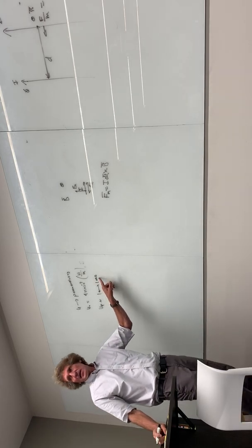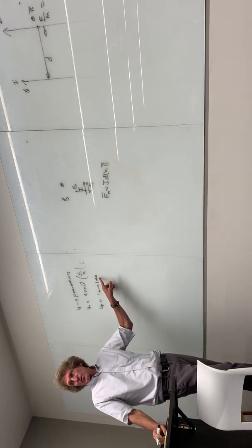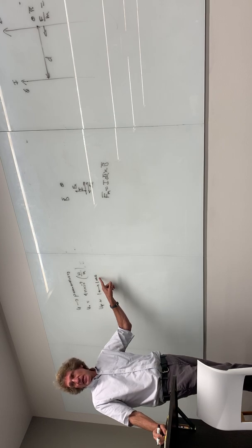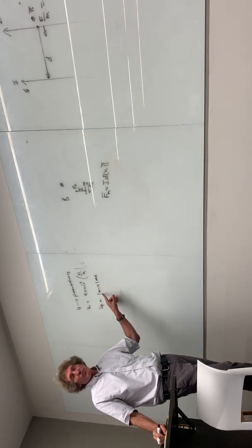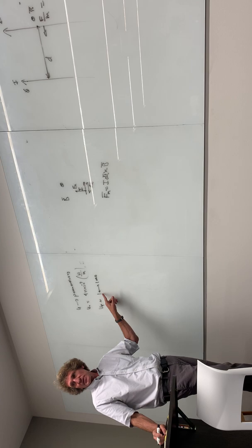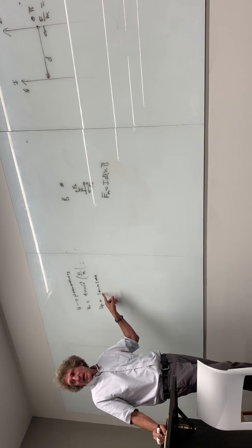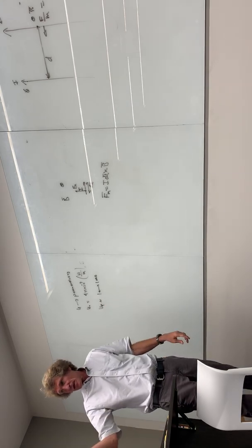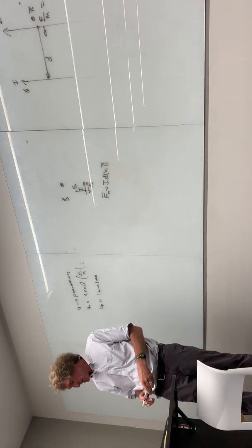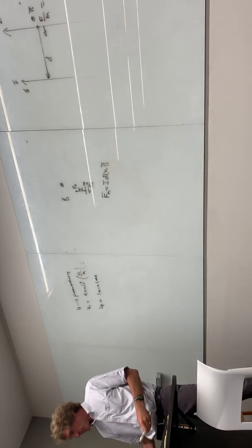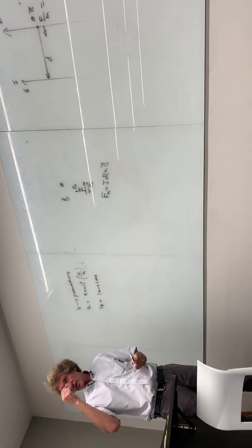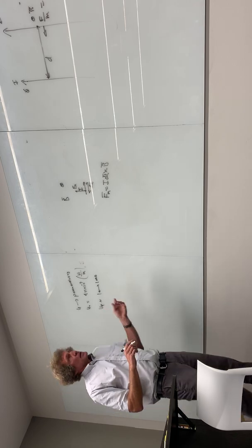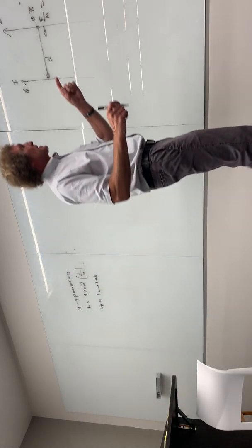For instance, any kind of thing used for iron cores for our transformers is about 1,000. It's laminated steel, it's about 1,000. If you have anything that's a typical dielectric, its mu relative is 1, so for all intents and purposes, it has no ability to store magnetic energy. This eraser is a good example. It has no ability to store magnetic energy more than free space would, but if you took a bar of iron, that has a lot of potential to store more because the mu relative of the iron is much higher. Anyway, so that's the magnetic field here.